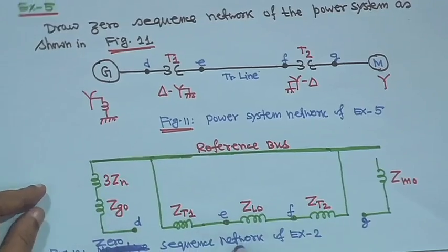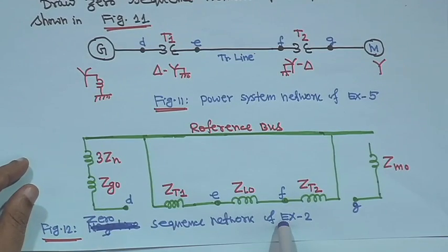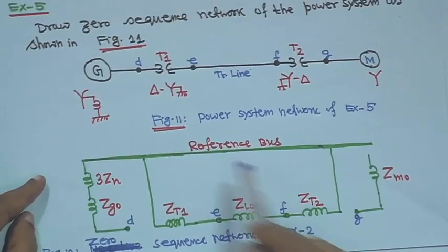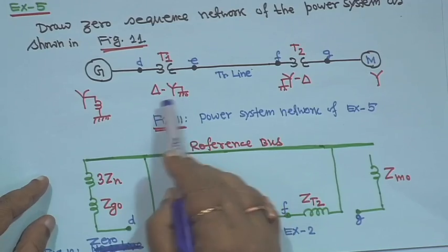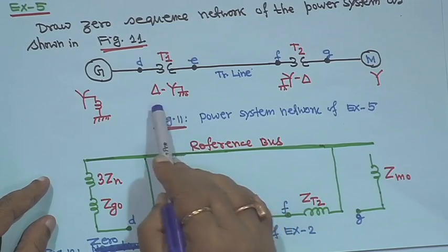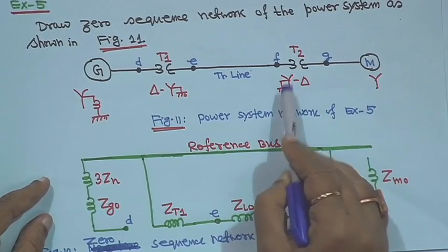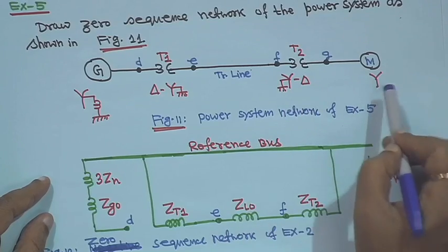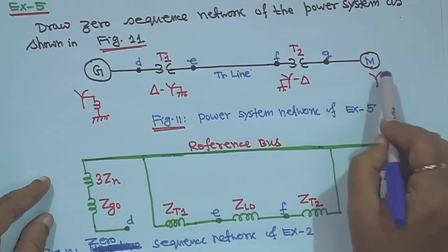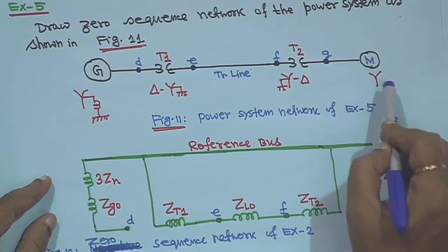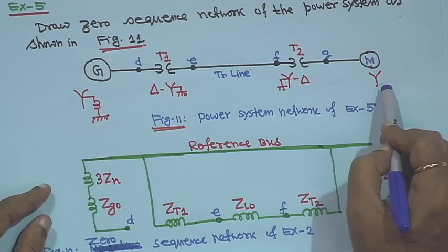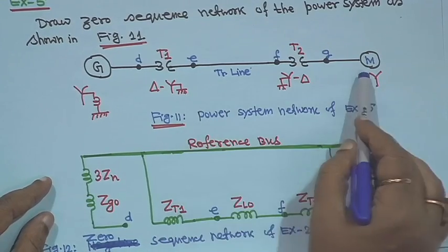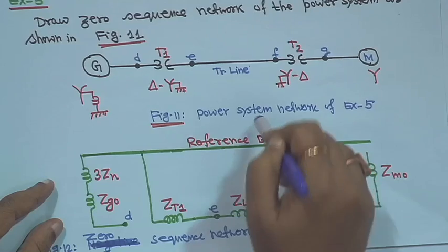My objective is to show you the zero sequence network, right. So, this is your delta-star connection, and the star is grounded; this is star-delta, the star is grounded, and this is a motor. The generator is supplying power to the motor, and this is star but ungrounded. You have to draw the zero sequence diagram. Parameters are not given, but you have to take something and make it.